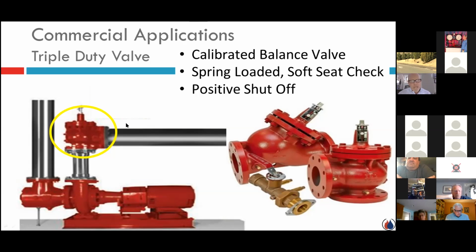So over the years, the practice was to take this balancing feature and back it down to slow down the pump, to back it up on its curve. But at the same time, if you think about it, that's also kind of wasting a little bit of energy. And so as ASHRAE and the hydronics industry look at that, they might come up with a different approach and say, look, let's put in the proper size pump, maybe trim that impeller to more appropriately fit the needs of the system, instead of consuming more energy than we need and then just eating up some of that energy right here with that balancing valve.